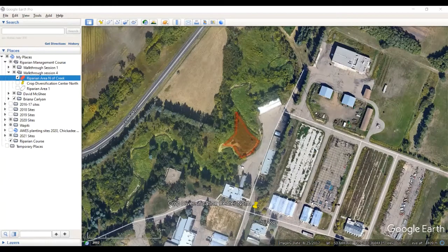So once you have your total area, you can do a little bit of conversions and determine, based on these spacings, what you need. Typically in a riparian setting, we tend to go with a little bit more dense spacing. So occasionally we'll do a 1 meter spacing, or sometimes even less than 1 meter spacing. So this is the relevant number of seedlings that you would be using per hectare. And you can design a little bit of a table to keep things organized for yourselves as well based on the particular area.